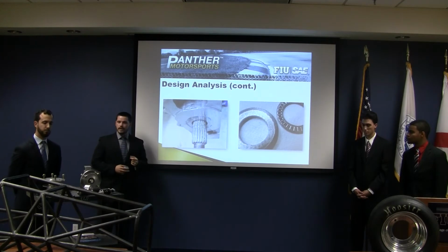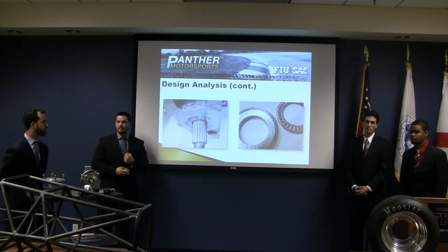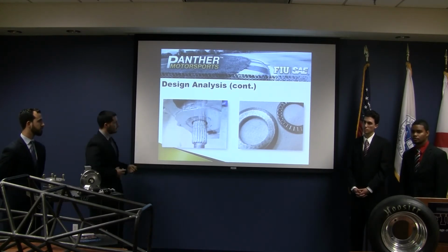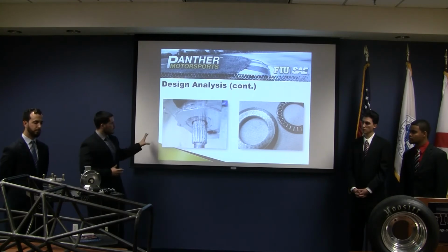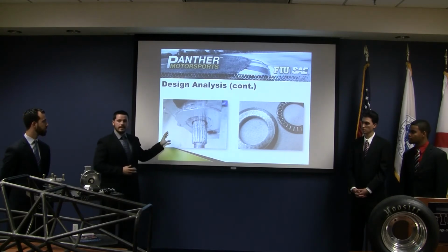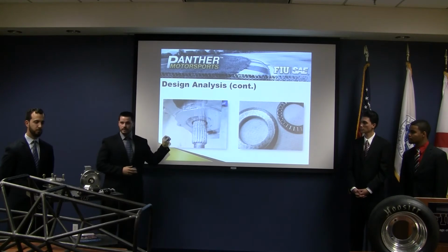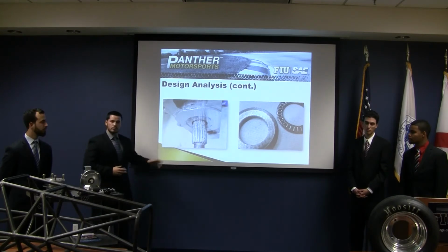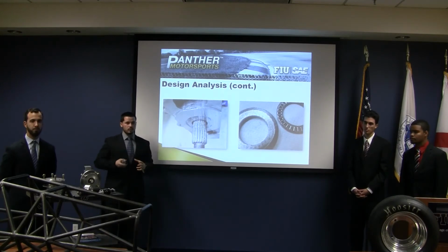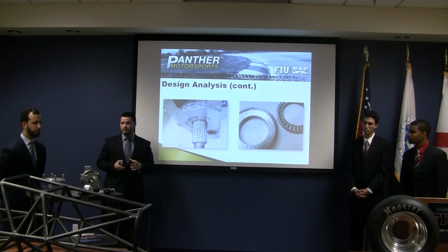Something that originally we did not consider for our project, but we later took it upon ourselves to assist the team in, was the hub situation. There was an improper use of a thrust bearing on the hub, which would cause the wheel to seize up when the lock nut was tightened all the way down onto the axle.